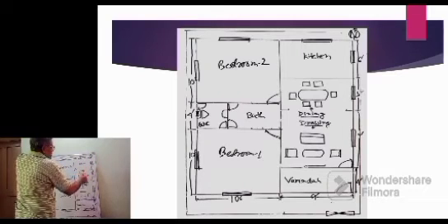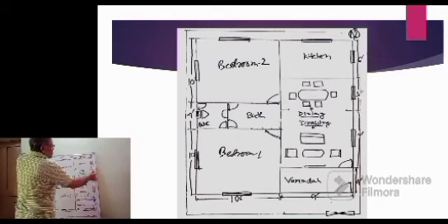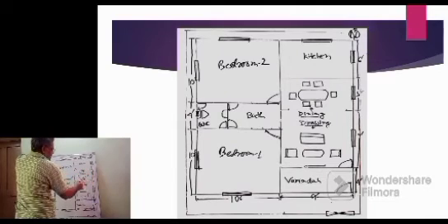So with the kitchen we are providing the dining also. So including kitchen and dining, it should be 100 square feet. It should not be less than 100 square feet. So it is 9 feet here, and it is 5 feet and 6 feet, 11 feet. So 99 square feet it is there. So we are providing the dining space here. Here it is a door to go inside the kitchen, and this one may be open.